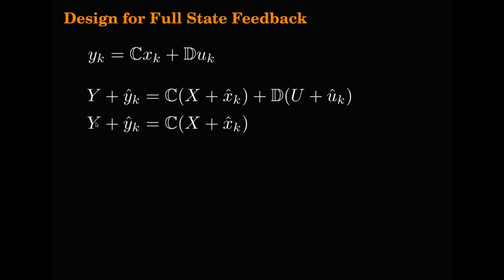So in the example that we discussed, in the case of a DC motor control, you have two state variables, I_a and omega. So let's say you want to control omega, then omega becomes Y. Omega becomes the controlled output, and you would like to set the reference for omega, so that Y approaches or becomes the same as the reference value with zero error. So in the steady state, Y will reach R,